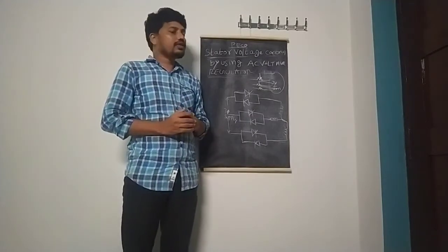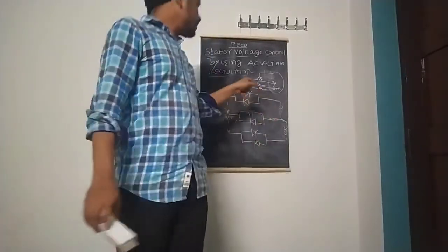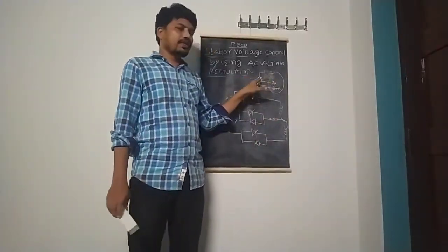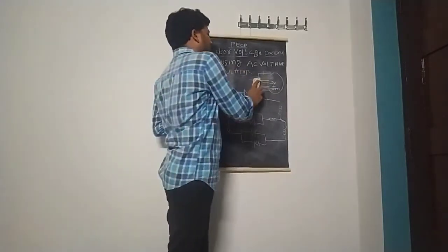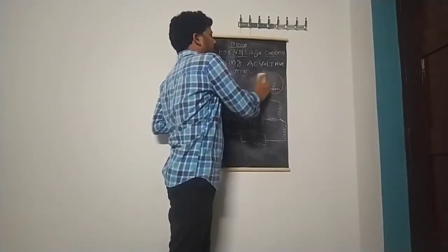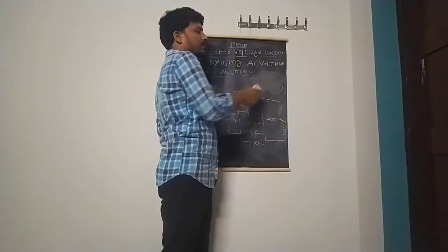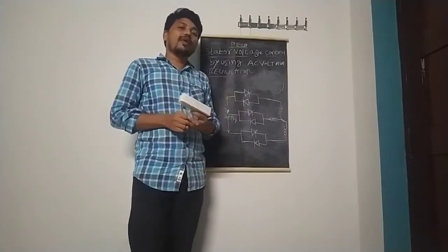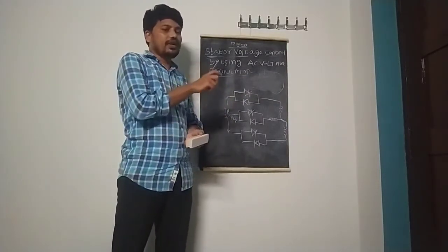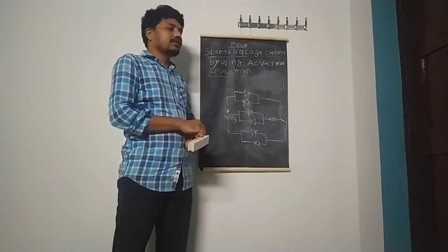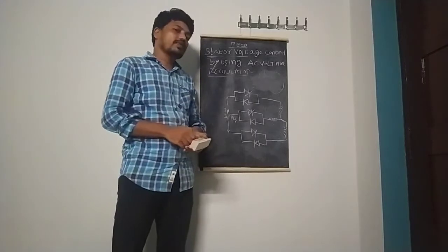So this is the main advantage of primary resistors while connecting the three-phase supply of the three-phase induction motor. But the drawback in this case is that, whenever the rheostat is adjusted, we can get the variable voltage, but the rheostat itself causes power loss. Due to the resistive property of this resistance, there is a possibility of high power loss. Therefore, the losses are more.